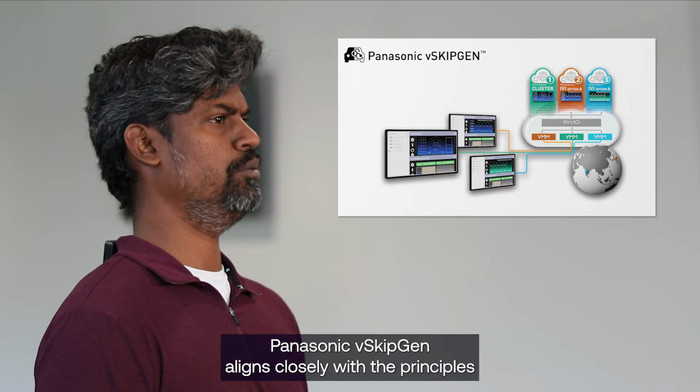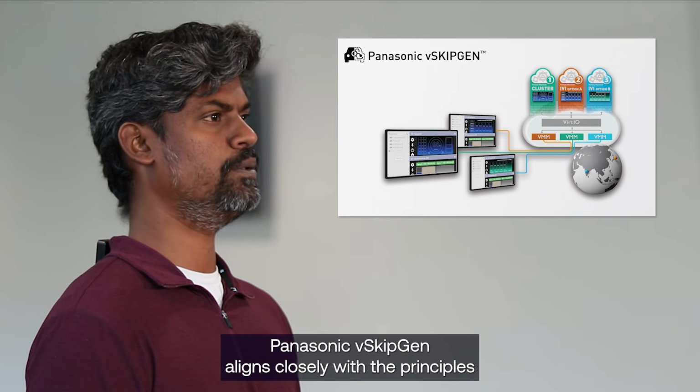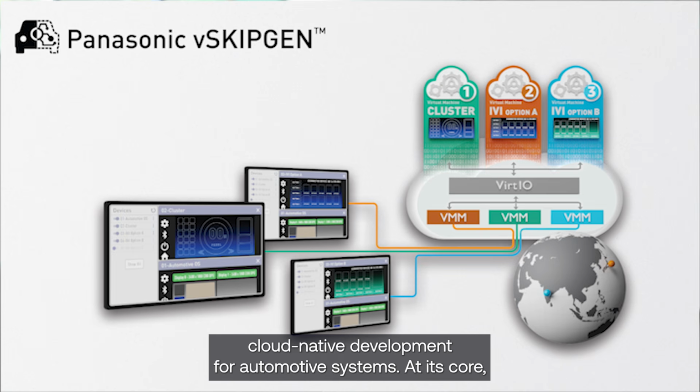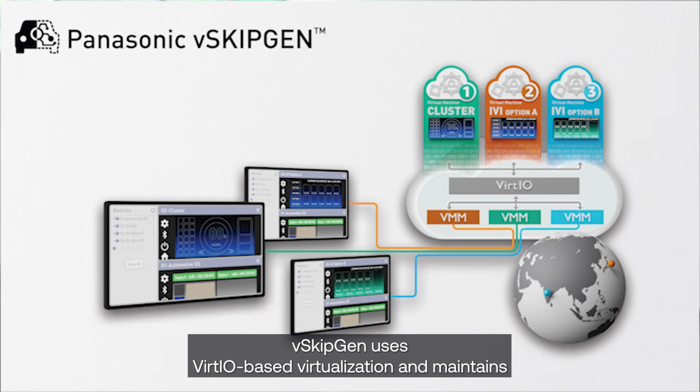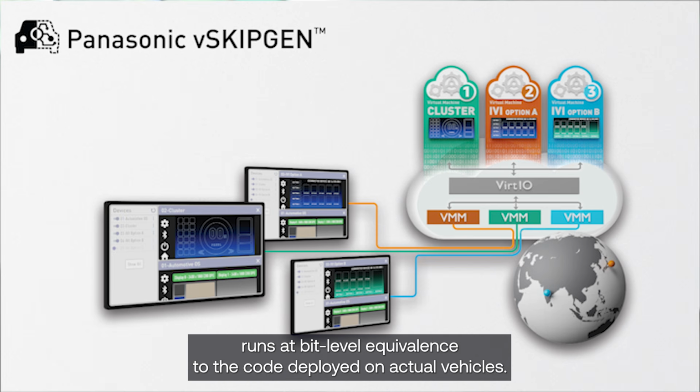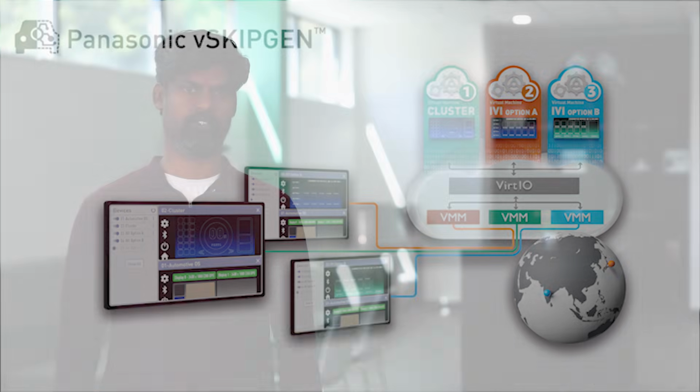Panasonic Automotive vSkipGen aligns closely with the principles of the SOAFEE architecture by enabling service-oriented, cloud-native development for automotive systems. At its core, vSkipGen uses VirtIO-based virtualization and maintains ARM binary parity, ensuring that code developers build and test in the cloud runs at bit-level equivalence to the code deployed on actual vehicles.